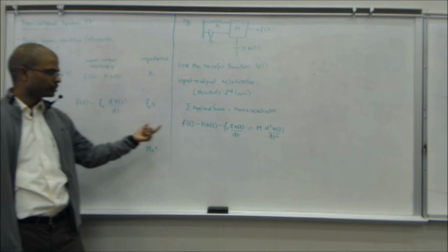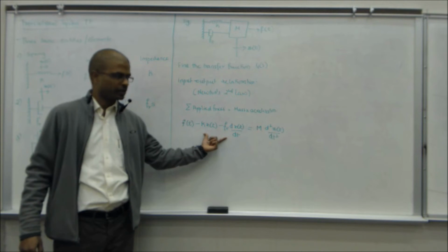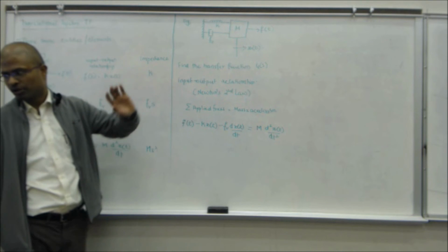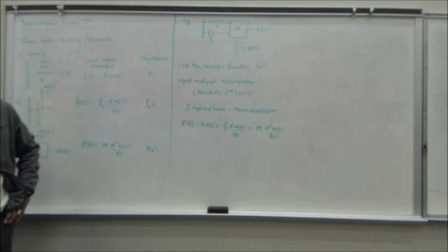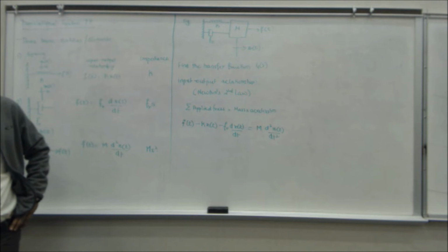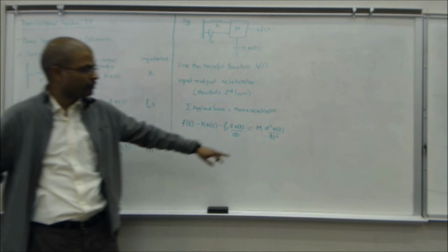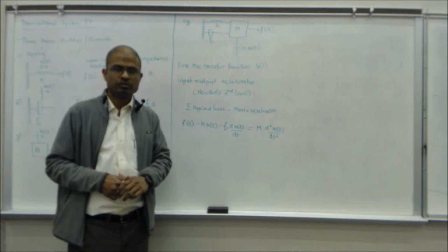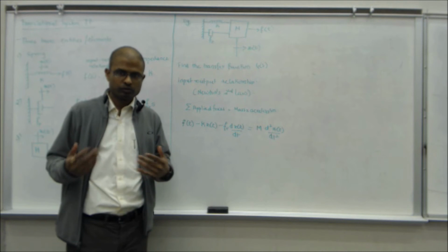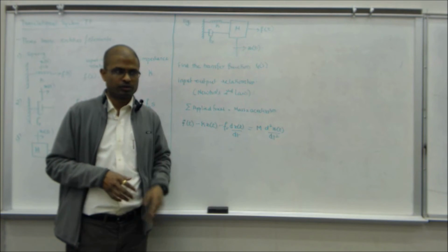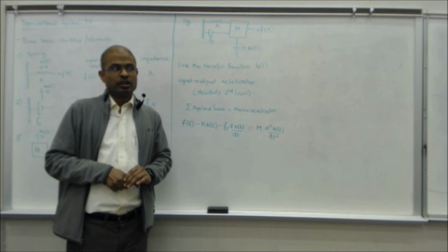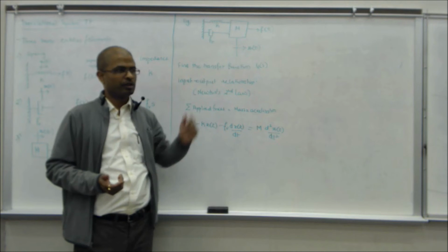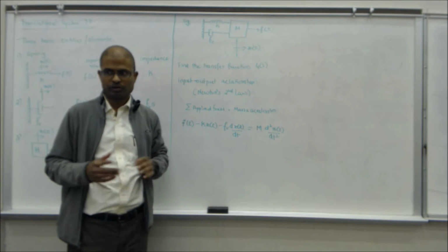Okay. So this is the left hand side, and this is the right hand side, mass into acceleration. Now, one of the things you need to notice here is, we ignore the masses of the spring and damper. That is the reason we just have this m. Otherwise, it has to be the whole system. You should ask such questions: what happened to the mass of the other system? In comparison to this mass, we assume the spring and damper are really negligible, so we just ignore that.